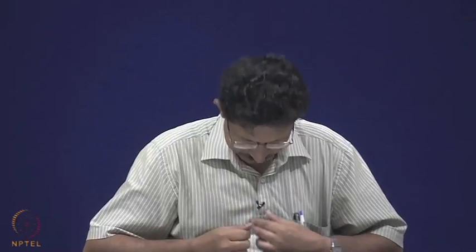And with this we can now extend our cross flow solution over a cylinder to a cross flow solution over the cone and complete the conical flow solution for any arbitrary flow, of course, within the framework of linearized small perturbation theory, and we can compute the forces. So, next we will compute the forces that act on a body either at axially symmetric flow or asymmetric flow.